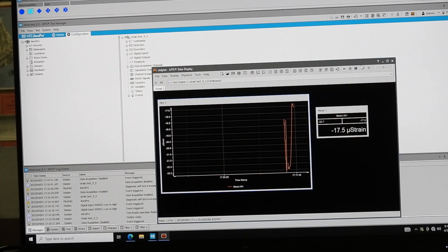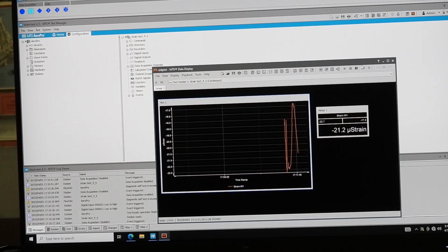It's just that it's triggering at above 3.5 volts. So if you want to recreate the digital input functionality, you can, but it will probably be more difficult to implement and maintain. So it's dependent on that 60 not floating.